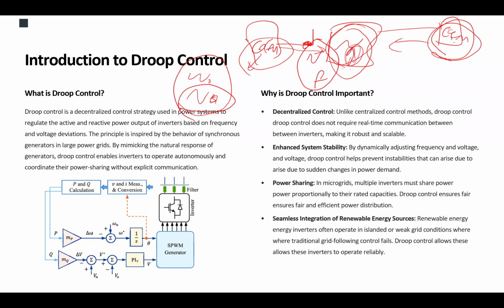Now, the other part is the seamless integration, because they don't have to synchronize with the grid. It's like a plug and play situation. They work independently, so they just have to connect to the grid, and they would catch up. They don't need a synchronization period like grid following to get synchronized to what the situation in the grid is and what settings they can have.